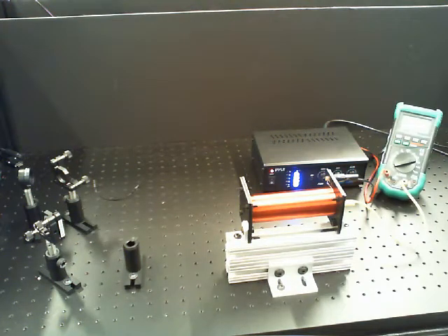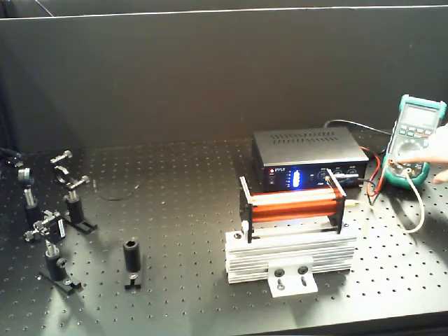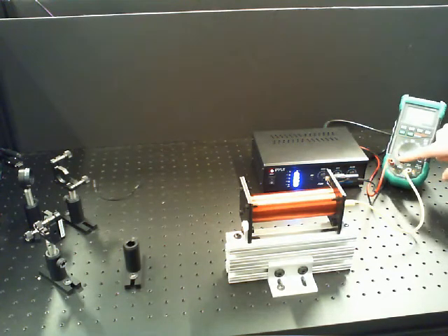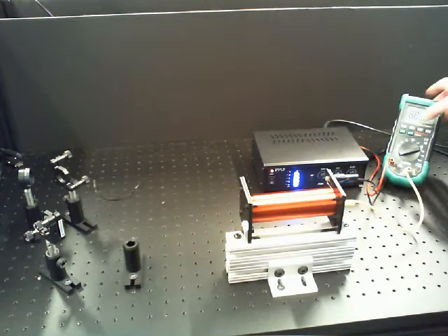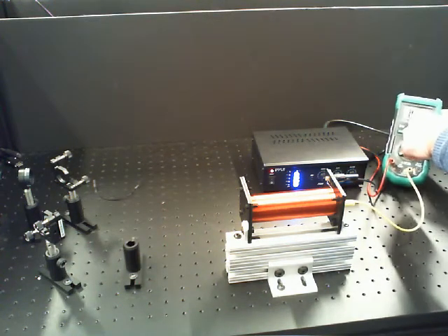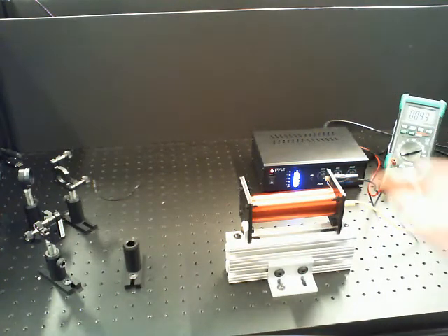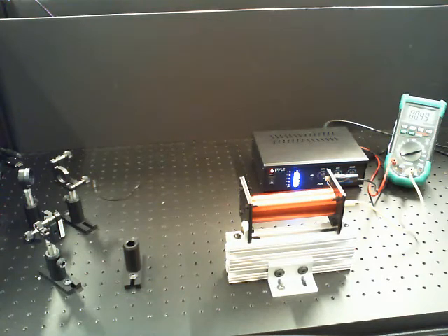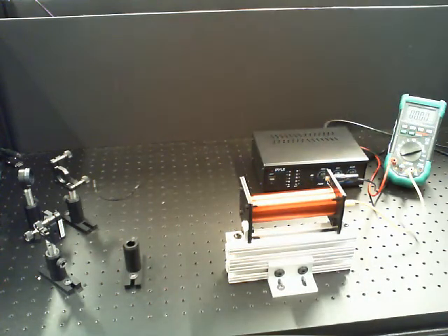Now, the digital multimeter will have to be in AC current mode. And you'll notice that there's only one current mode here, amps or milliamps. But because we'll have a reasonably high current, we'll be on the amp setting. And to distinguish between DC and AC current, when you have it set to the amp setting, you have to push this select button. And that will allow you to select between, I'm not sure you can see this, DC and AC by putting the select button on. Okay, so we want 1 amp of AC current.